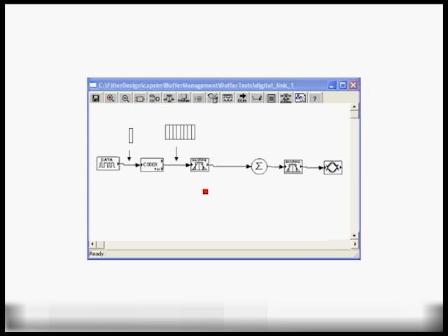So this block, this Nyquist filter block, for example, the square root Nyquist filter block here, runs at its natural rate, whereas the binary data generator runs at its natural rate, which is at the baseband, the bit rate, and the filter runs at its rate, which is 8 times the bit rate. So each block runs at its natural sampling rate.